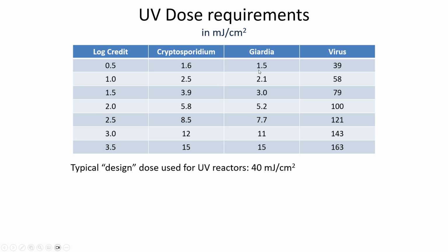There are certain viruses, like for example the adenovirus, which causes colds, is just one that I guess it's maybe because it doesn't have very many adjacent thymine dimers, or it may be something related to the structure of that virus. But there are a handful of viruses that require a really high UV dose. But luckily, those same viruses are pretty vulnerable to chemical disinfection. So if you use the UV to mainly focus on crypto and Giardia, and you use chlorine to focus on viruses and bacteria, then you'll have a good kind of multi-layer approach to disinfection.